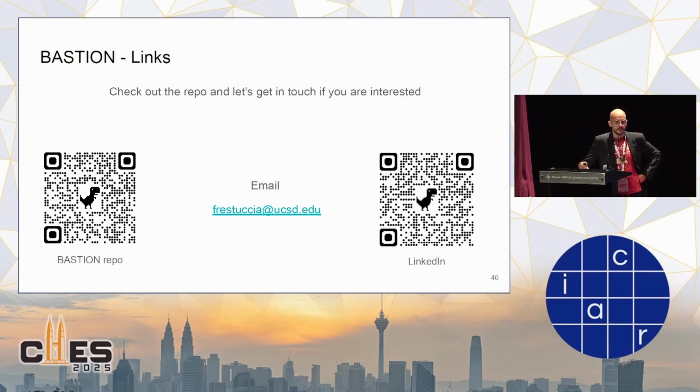No, by design it's plug and play with respect to the network on chip, so it's transparent. The IP doesn't even know that there is an access control system. It's the same interface; from the point of view of the network on chip, there is no change. That's why we decided to put it inside the access control system. And the memory addressing is the same, with no need to change it.